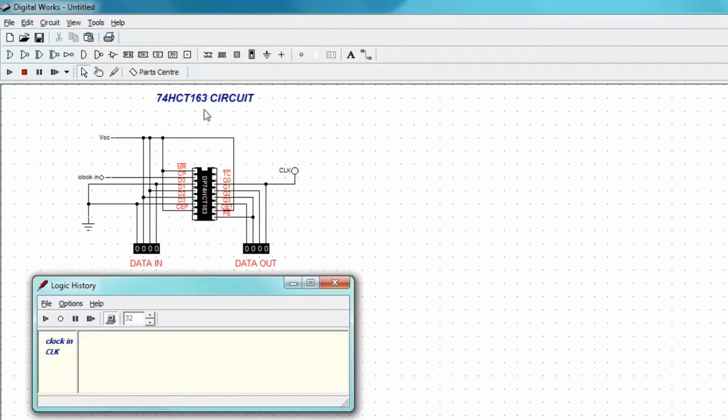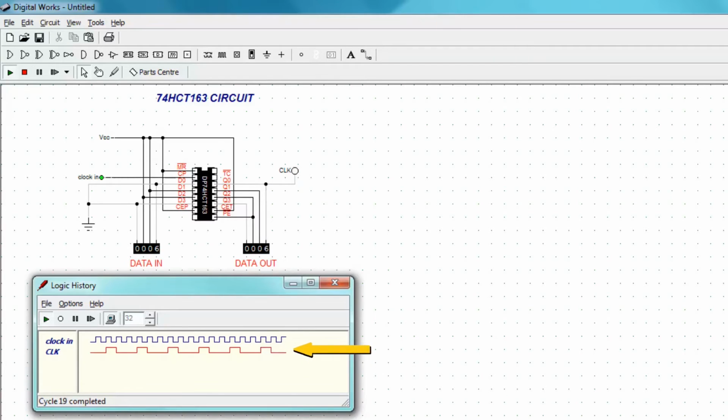Now, if we simulate this, you can see we have a one-chip solution for a 33% duty cycle processor clock coming out of bit 0. Let's see if we can also get a peripheral clock out of the same single chip.